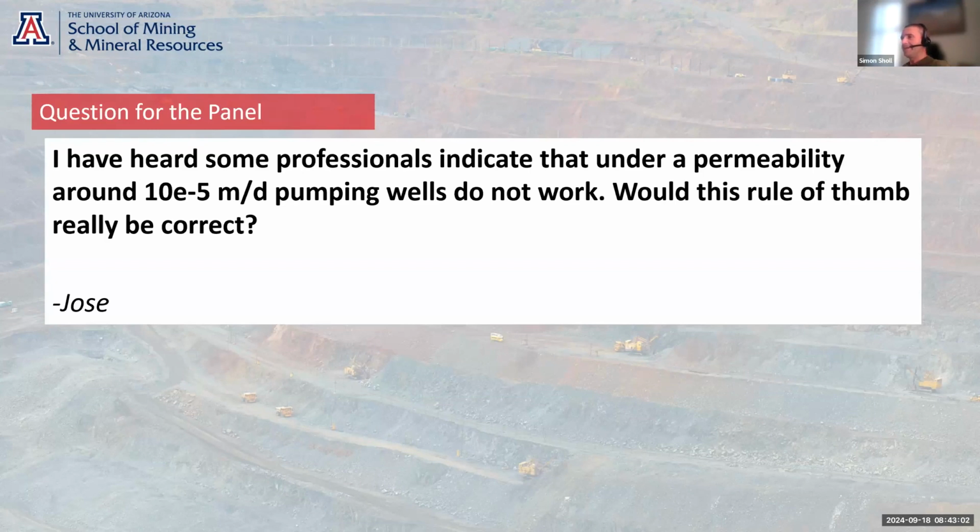So you're better to get a much clearer picture of the interaction of the fractures, the connectivity of those fractures. As Jeff said earlier, depending on where you intersect those fractures, if it's high up in the borehole, you may pump a well for a few weeks or a few months, but once it's desaturated, you're not going to see much water from it. Whereas if the fracture zone is very deep in that well, it'll be a more productive hole and last longer. So I think hydraulic conductivity isn't really the best way to describe the characteristics of a lot of environments.